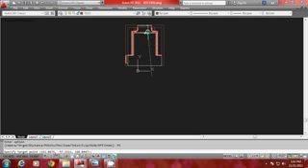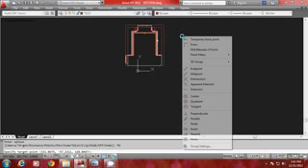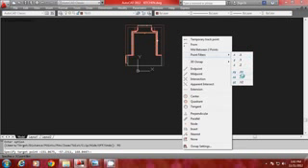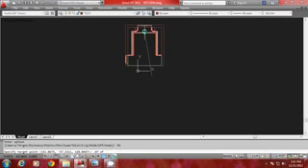So I'm going to define a target point. If I simply make a click here, this point will be taken on the XY plane. So in fact, I want the target to be elevated from the XY plane or from the floor level through a certain height of say 150 units. So I will define the target using point filters. So I'll go to shift right click, go to point filters, and I'll select .xy and I'll pick a point over here. So only the X and Y coordinates of that point are selected.